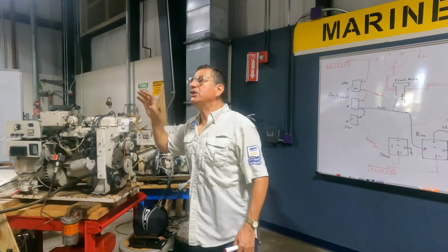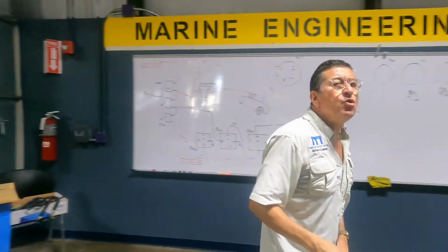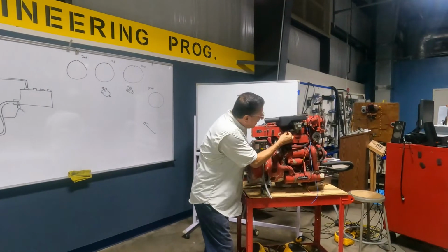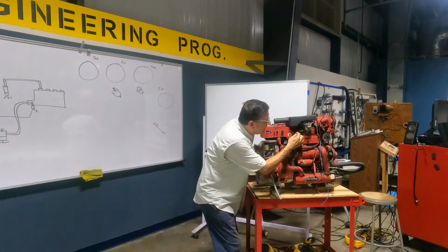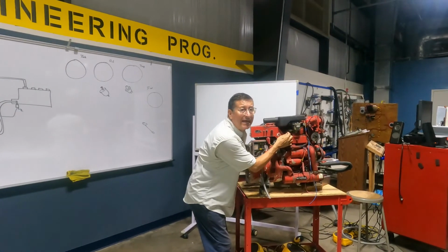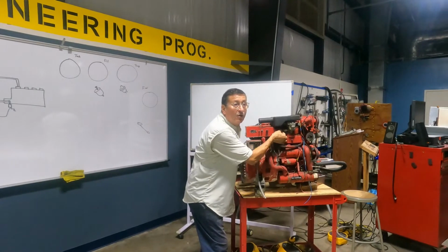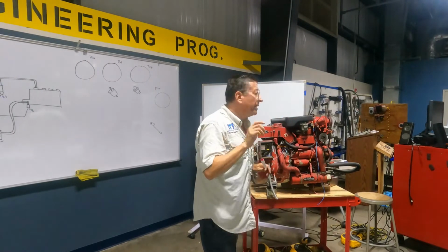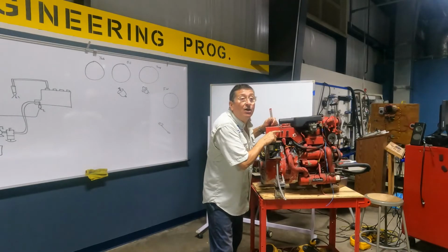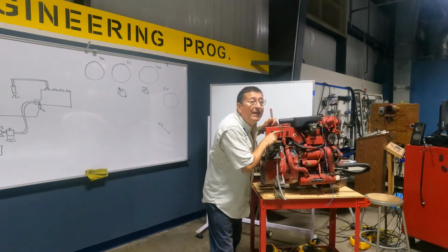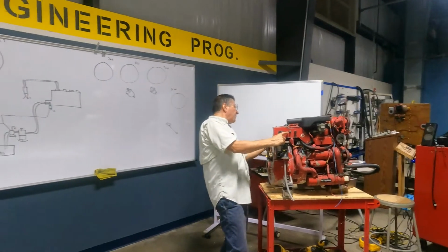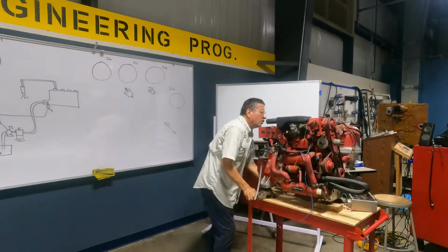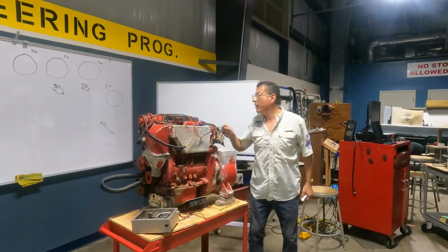Hey, my friend, is your engine gasoline? Yes, my engine is gasoline. Can you go into the carburetor and check where that solenoid is? Oh, it's here. Can you turn on the ignition switch and verify if it's clicking? Yes, it's clicking. All right, the solenoid is clicking. Clicking indicates that it's working, apparently. When you turn on preheat or ignition switch, preheat, preheat, you hear the pump? No? Okay. You don't hear the pump when you preheat.